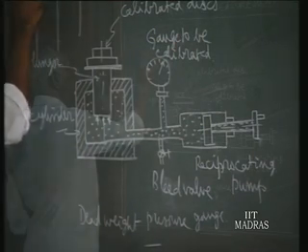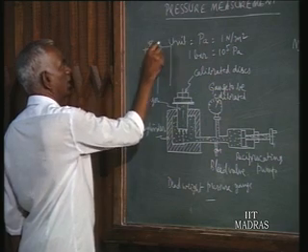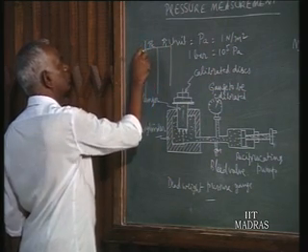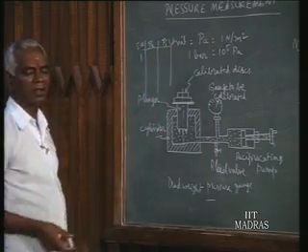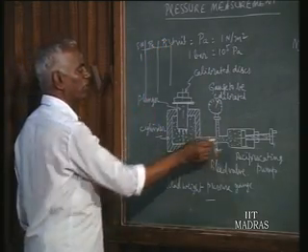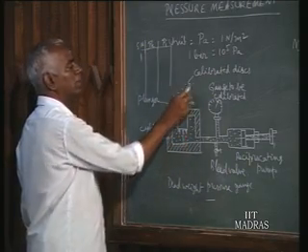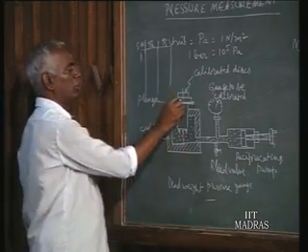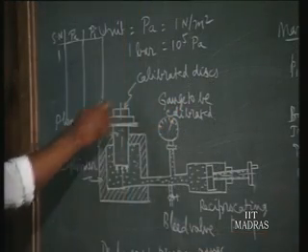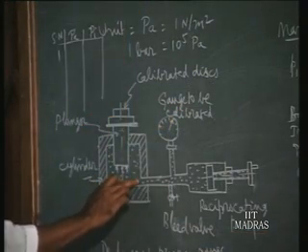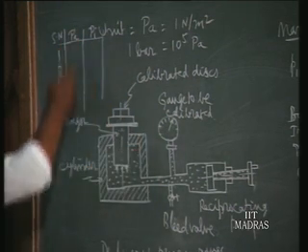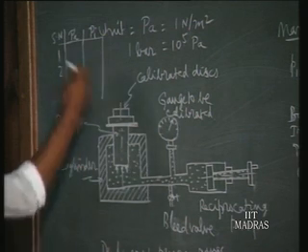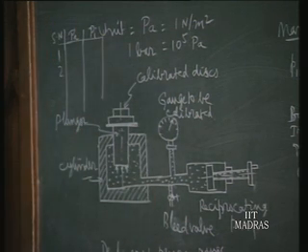So we can conduct this calibration, that is true pressure PR and indicated pressure PI. This is the serial number. Like that, whatever we have learnt under static calibration, we can develop different pressures here by adding more and more calibrated discs. Each disc has some pressure written on it. If we add 4 or 5 discs, we add those pressures together. That is the total pressure developed, and we note the true pressure and the pressure indicated in the instrument. A set of readings can be taken, and again from the high pressure we can go back to the low pressure. That is the way we have learned static calibration. It can be done here.